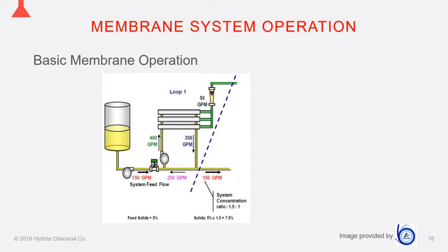Okay, so from here, we can just look at the numbers. We've got 150 gallons going in. The pump needs 400 gallons a minute. So if we just go up to the pump, we've got our 400 gallons a minute. We come through the membranes and we've permeated 50 gallons a minute. What goes in has to come out, and we've got 350 coming down to our baseline.